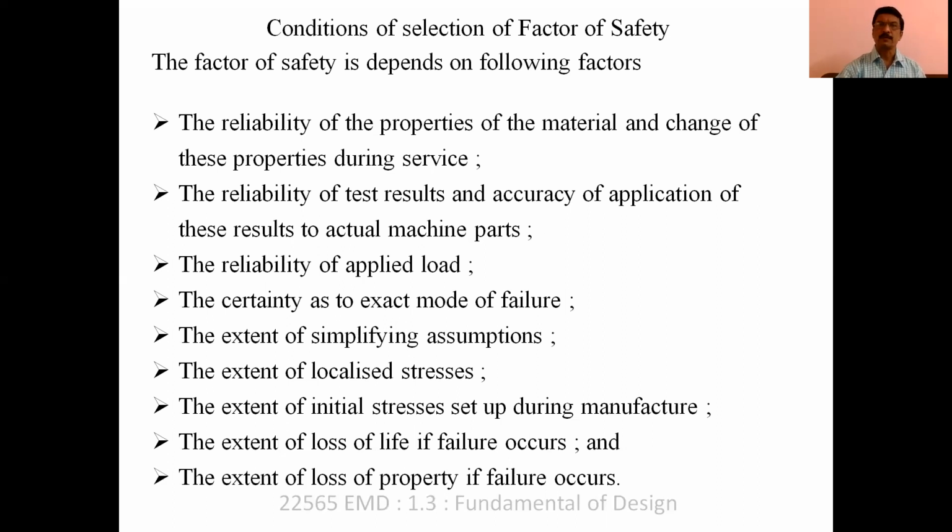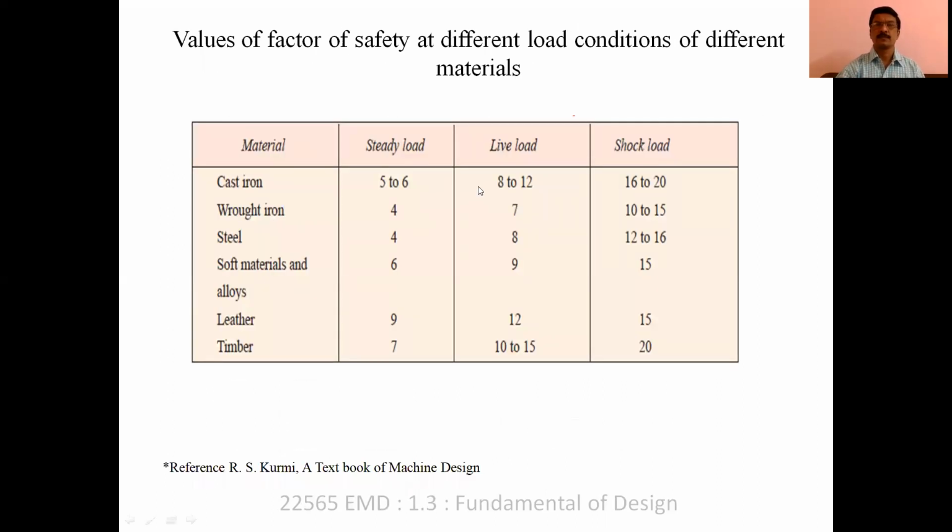Values of factor of safety. As we know, the values of factor of safety also depend upon what kind of load is on that particular component and what the material is. Now here you can observe the material and different kinds of load. Here steady load has a lesser value of factor of safety. If you go for live load, the factor of safety is going to increase.